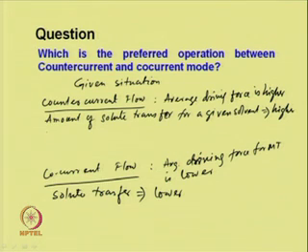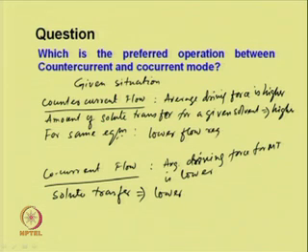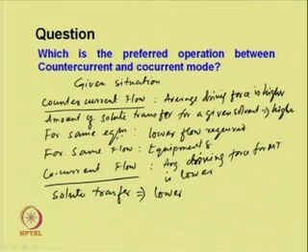And if we consider the same equipment, a lower flow is required in case of counter current flow compared to the co-current flow, or if we keep the same flow, then the equipment size required is small.